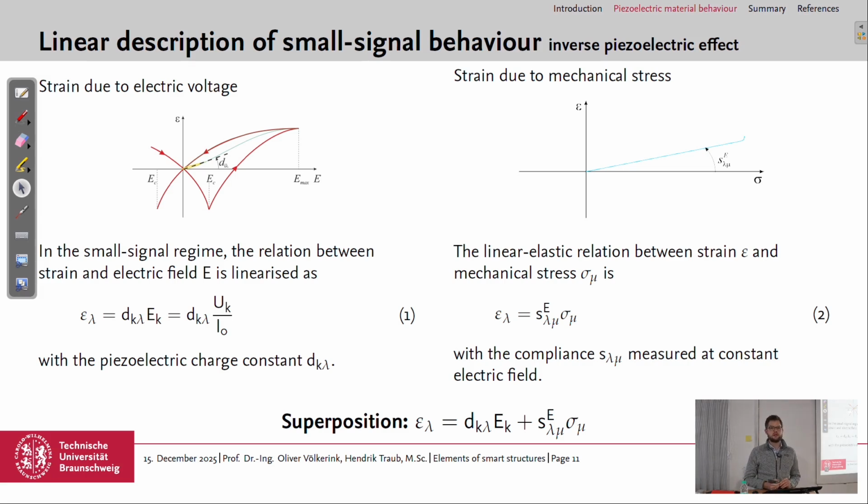If you have the piezoelectric material not, let's say, integrated into a material, and also no clamped or blocked boundary conditions, then it could move freely and does not build up any stress. So we measure the blocking force or the blocking stress due to the pushback of the force.